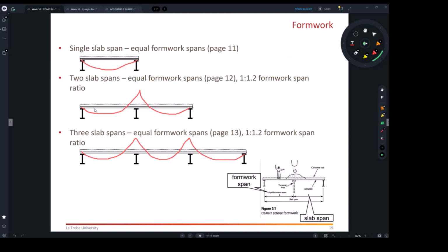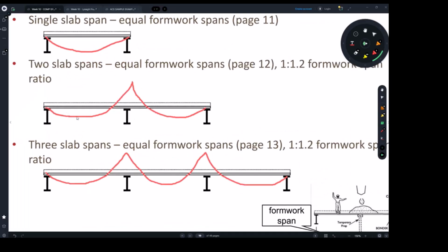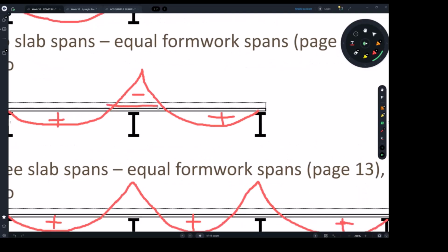So the decking, yes, it will help us to resist the positive bending. Usually in civil engineering, the positive is at the bottom. You remember? That means the bending which is under the slab, in the diagram, we call it positive because it's going to be tensioning the bottom and compressing the top. Now the negative bending here needs steel at the top to resist, so that's why we're going to have top reinforcement as well.